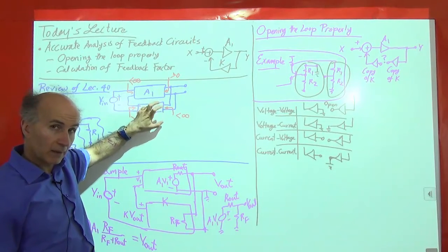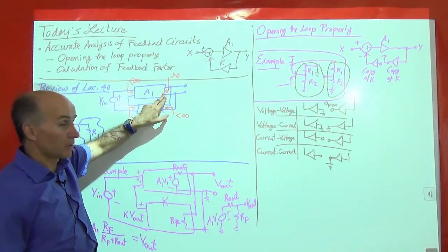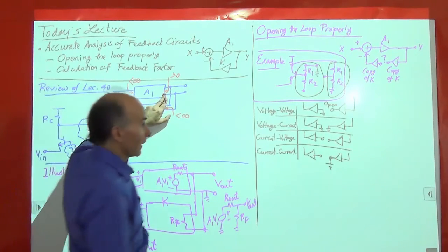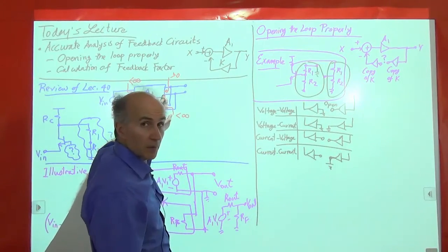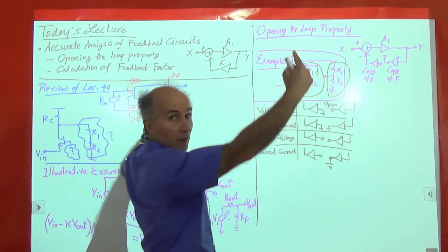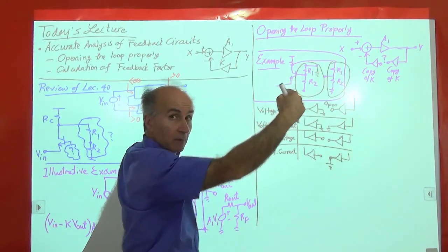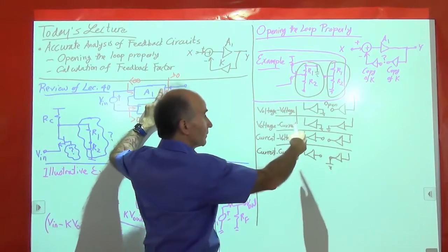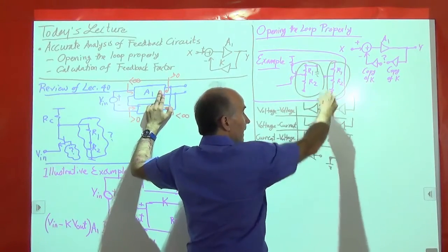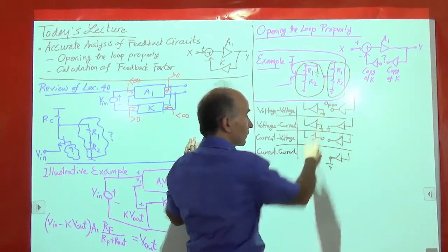So ideally, this circuit sees the output impedance of this guy, which is close to 0. That's why this copy has an input that's connected to 0. Because we think, well, originally this was connected to the output of the amplifier. And the amplifier has a very low output impedance, hopefully, right, this circuit. So now that I want to separate it from the amplifier to have a proper representation, I'm going to short this to ground.